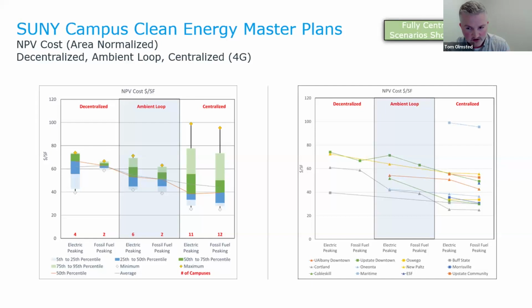Or, if we're looking at something like a wastewater treatment plant, effluent, it's sort of ambient temperature, but it really comes down to the flow. A very high volume of heat that can be tapped into for a heat pump relatively cost effectively. So where you have high heat or high flow available in a consistent way that can be more cost effectively harnessed. So the quality is tied to either the density of the heat or its volume. Is that a fair way to describe it? Yep, exactly. Great.